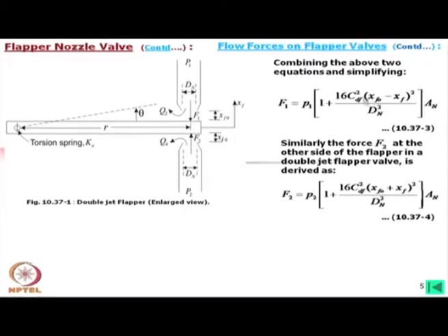So, physically this initial distance minus this spool movement will be used to find out the curtain area. In this case, due to this motion, this height is being increased, so this will be a plus sign here. Now, if xf itself is negative, then automatically this will be corrected. So, these equations we can use, this is the general form of the equations.